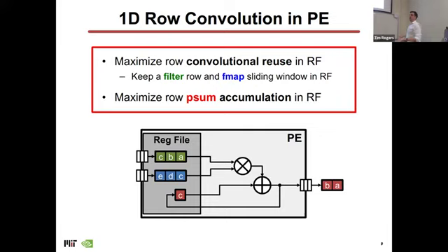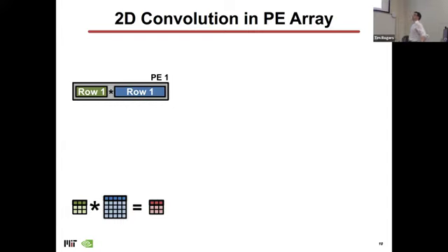It turns out that this trade-off is usually good, at least on the networks that they studied with their accelerator. So then how do I put these things together? I've got a bunch of processing elements. Let's say I'm going to do this in a row-centric way. So I'm going to devote PE1 to doing row 1 of the computation.